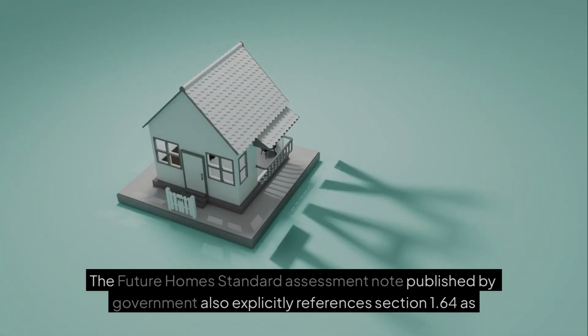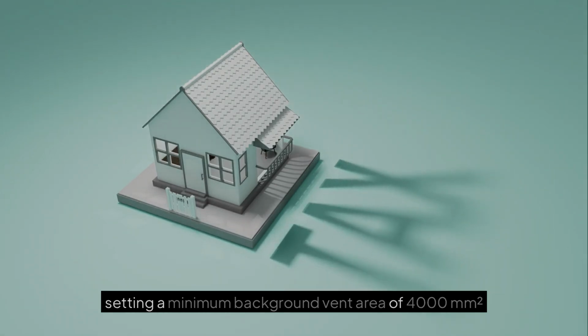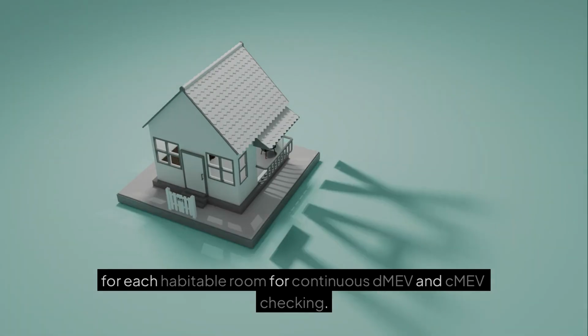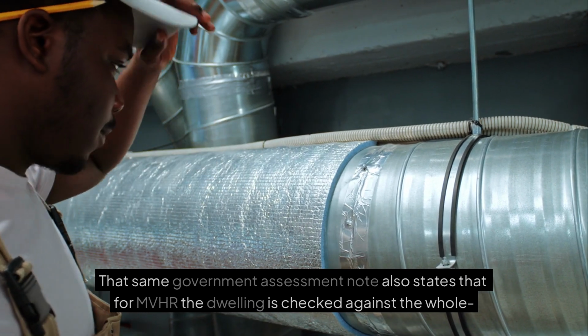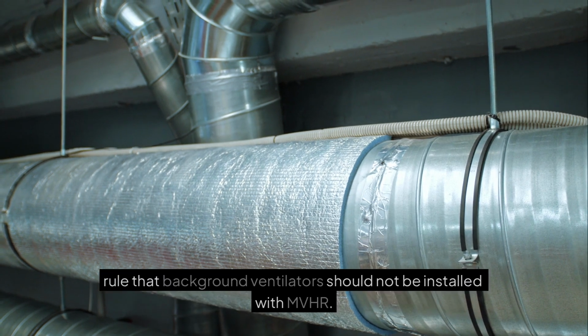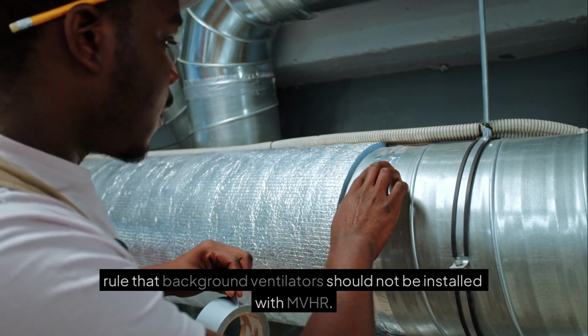The Future Homes Standard Assessment Note, published by government, also explicitly references section 1.64 as setting a minimum background vent area of 4,000 square millimeters for each habitable room for continuous DMEV and CMEV checking. That same government assessment note also states that for MVHR, the dwelling is checked against the whole dwelling ventilation requirement, and it flags the Part F rule that background ventilators should not be installed with MVHR.